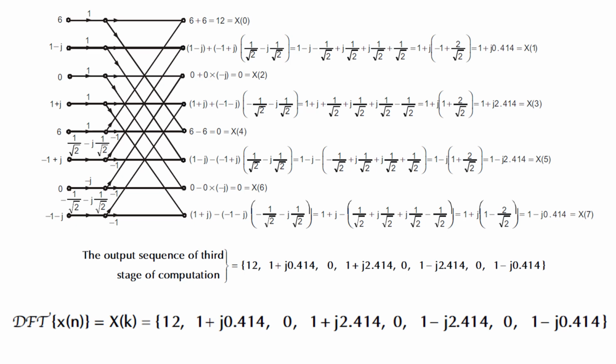This is how we have to calculate the DIT algorithm. So first we have to find the given N-point, which is a power of 2. Here we have got an 8-point sequence. So 2 power 3 will give me 8. So the number of stages is 3. From the stages we can calculate the stages separately, and the final stage output is the DFT of the given x of n. So for DIT, the input is in bit reversal sequence and the output is in normal order.